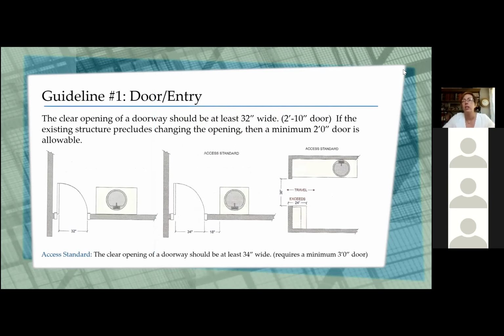The guidelines start off with talking about entry into a bathroom. Bathrooms a lot of times in these areas, when they were the small 5x8s or even smaller than that, are tiny to get into. What we are looking for is predominantly to have at least a 32-inch opening to be able to get in. It's a comfortable door to walk through. I myself will share that I have put 24-inch doors on bathrooms, but they are tight to get through, especially if you have a larger human being that's trying to walk through it.